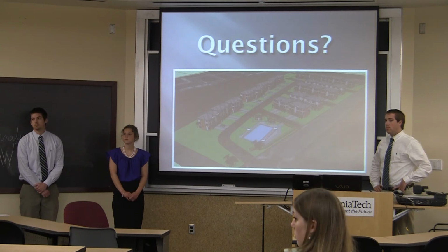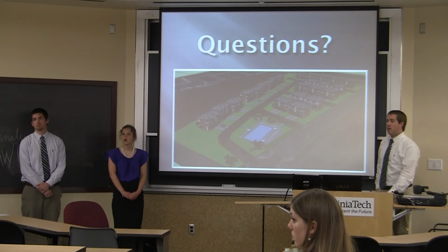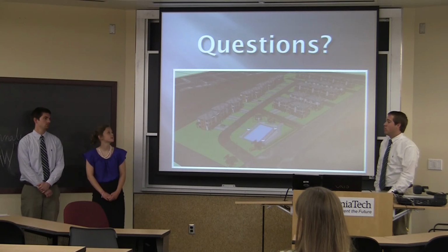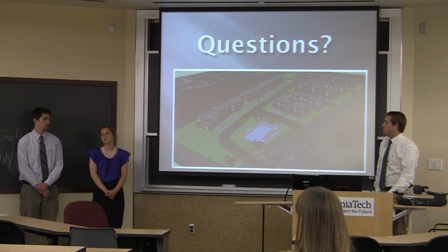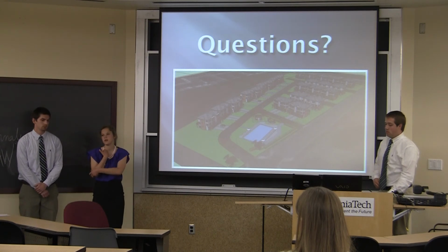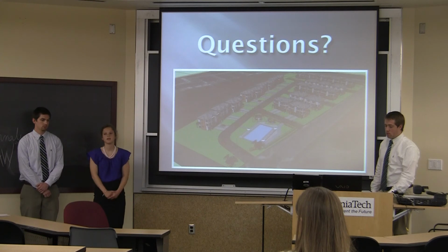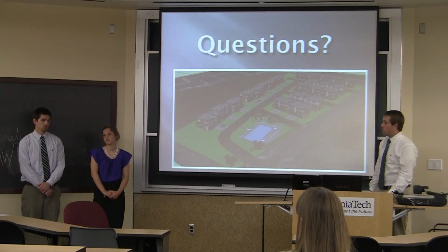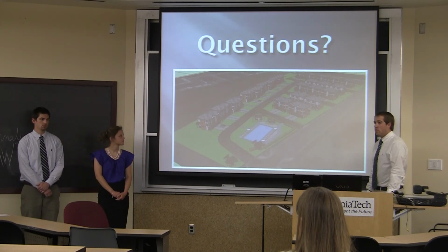Did you see any opportunities for value engineering? We did discuss that actually in our report. Definitely trying to balance cut and fill will be the key thing to reduce costs and to try to go with the existing grade if possible.